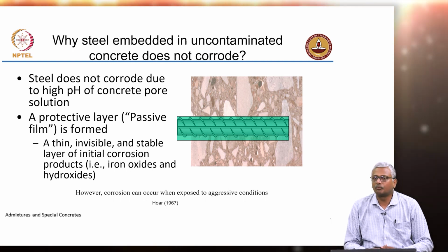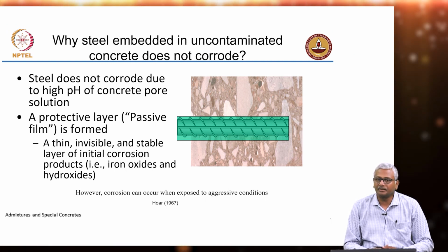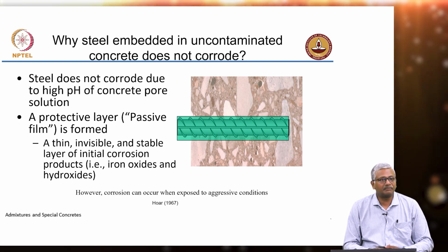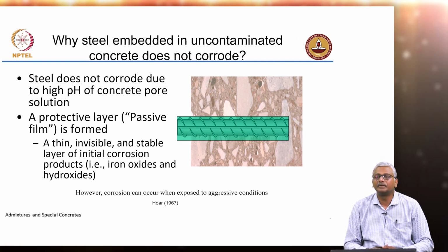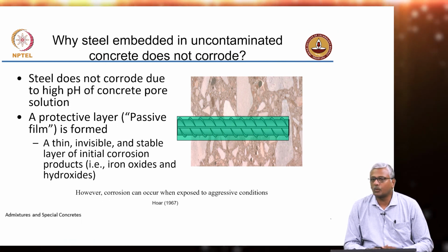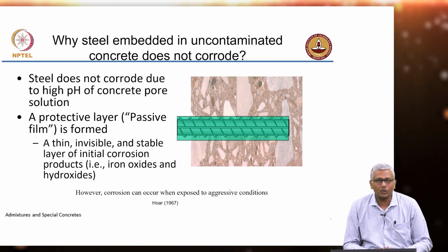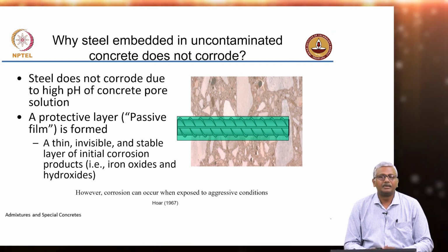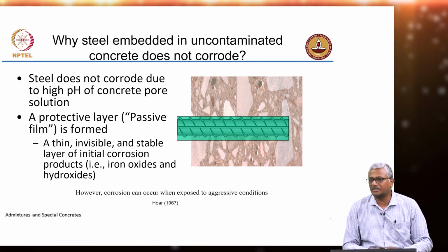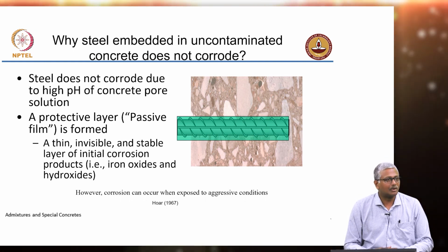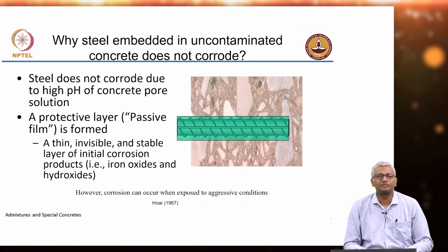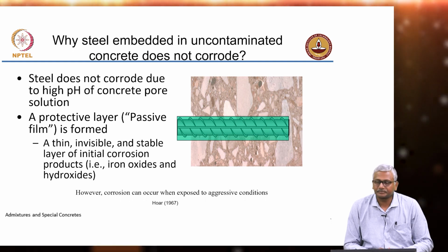Over the years, we have moved on from mild steel to cold rolled steel, and then finally today we are using what type of steel? TMT, but the actual correct name for that is quenched self-tempered QST steel, right? The common name is TMT, thermomechanically treated, but that's not really a correct name because most steels are thermomechanically treated, right? Every steel has some thermal treatment, some mechanical treatment.